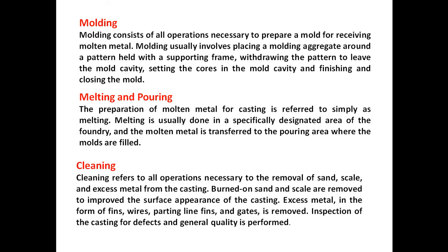Okay, so what is cleaning? Cleaning refers to all operations necessary to remove sand, scale and excess metal from the casting. Burned-on sand and scale are removed to improve the surface appearance of the casting. Excess metal in the form of fins, wires, parting line fins and gates is removed. Inspection of the casting for defects and general quality is performed.